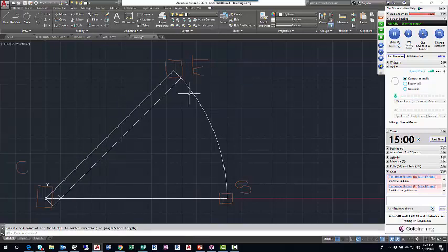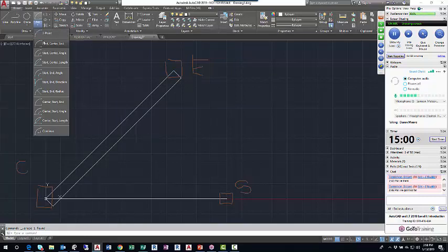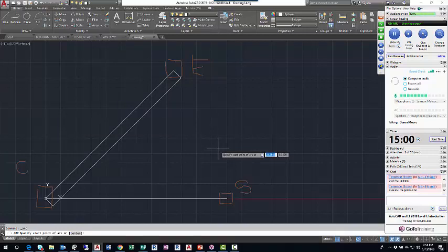And that places that as about as well as it can be placed on this drawing. And then I'll erase the horizontal line. But again, I'm going to erase that and do it again. So opening up where arc is, I'm finding start, center, end. I'll left click on this. The command prompt says to specify start point. I'll left click the right end point of the horizontal line, left click with my object snap. Specify center point of arc. I'll left click the left end point of that same horizontal line.